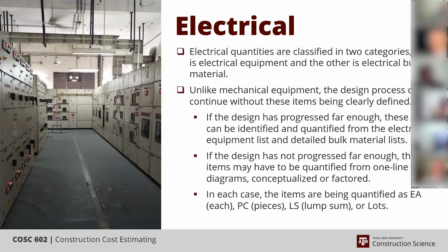The electrical follows that in the design process, because it's not until you know the size of your motors and the distance they are from your power sources that you can really size your cabling. And it's not until you know all that you really can start sizing your transformers. So E&I tends to lag behind in the design process because of the necessity for the motors and the lighting and the electric users to be identified fairly well.